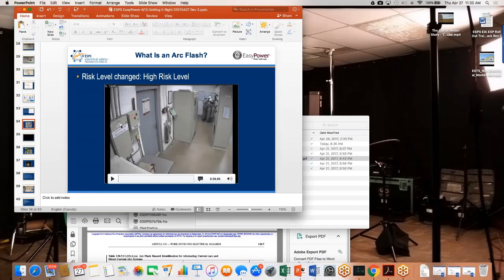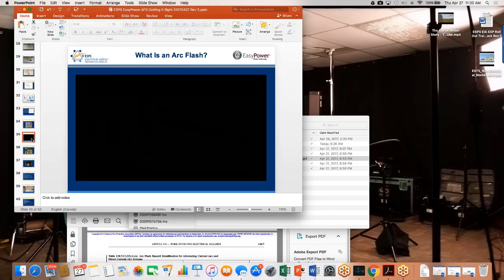There was an arcing fault probability. He was doing energized repair and alteration, which, first of all, shouldn't have been done energized. But again, there were no practices. So what happened is the worker proceeded to do the work.